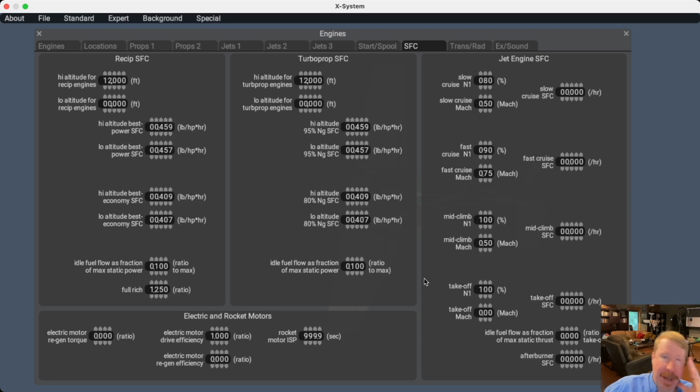When you just have to say, our engine's running too hot, dump in fuel, we don't even burn, it'll evaporate and cool us down. I mean, that's pretty bad engineering. But that was the knee-jerk reaction they came up with, and it did let you run a turbocharged engine at 310 horsepower without overheating it, so I guess it worked.